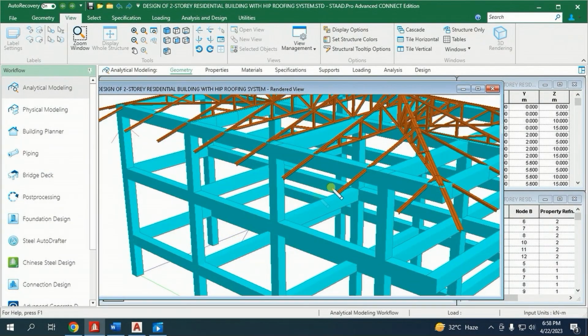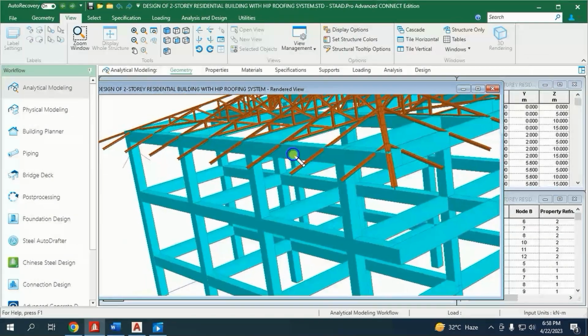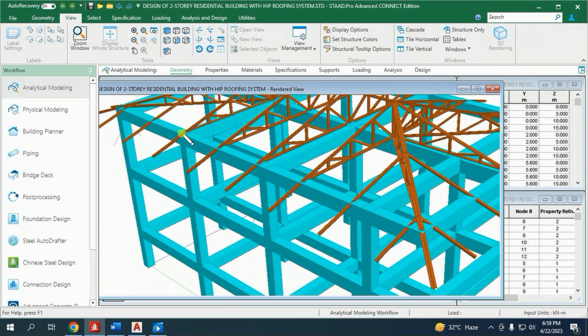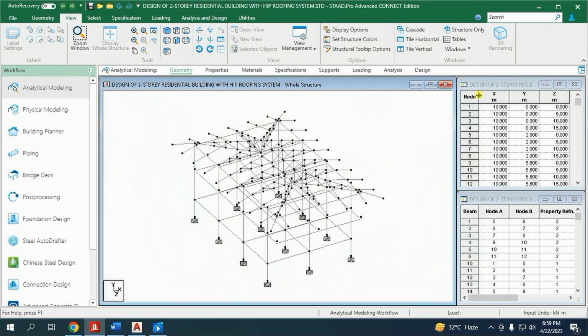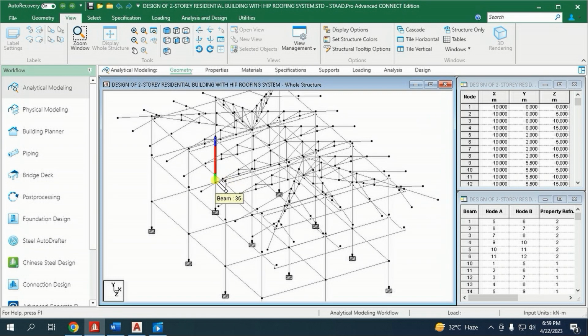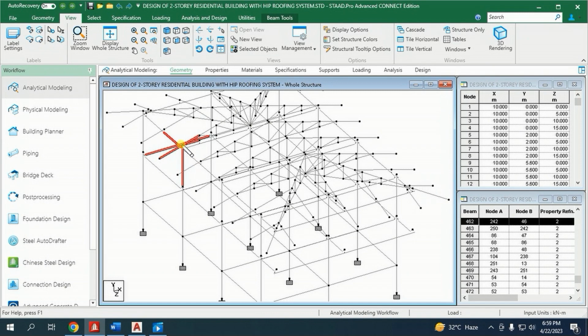If we notice, the trusses here are deep seated, and we are going to offset these trusses upward by, let us check here in our sketch how much we need to offset the trusses to remove this unsightly 3D view. So this is the STAAD model here, this is the column, and this is the top chord, and their connection is this node here.